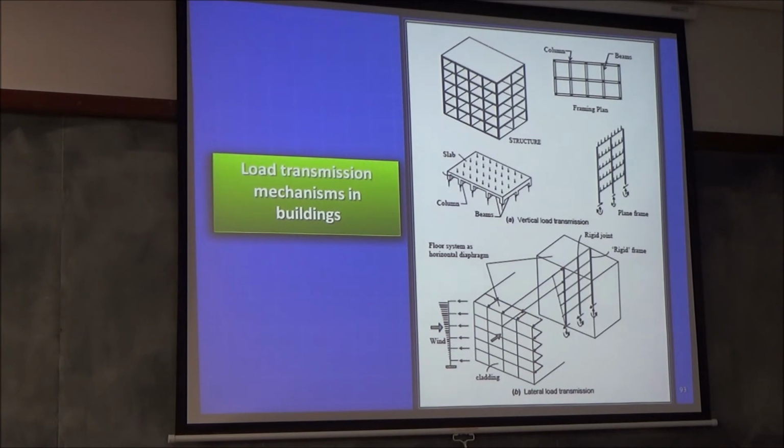Tributary area. You say that the exterior frame, if this is equally spread out, will take half the load compared to the interior frames. Yes? Right? Now, is it a correct assumption? I'm glad we are raising this topic. You have to find lateral loads on the frame, right? But how do you arrive at these lateral loads? That's where 3D analysis will give you a better understanding, but you can use your common sense.